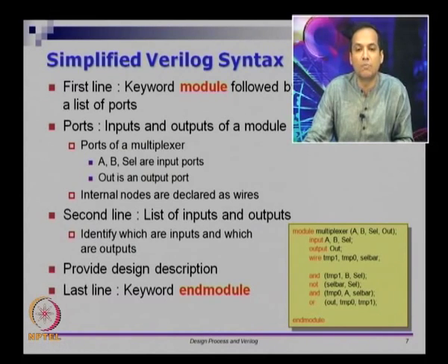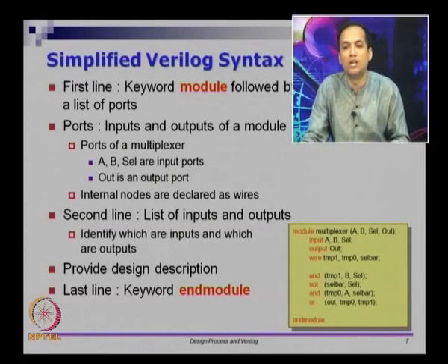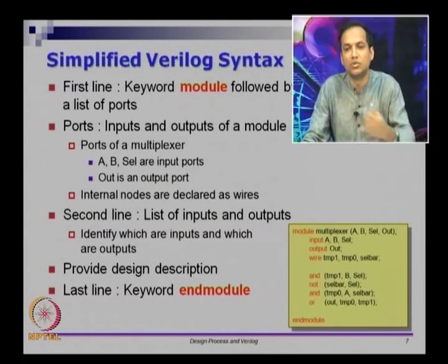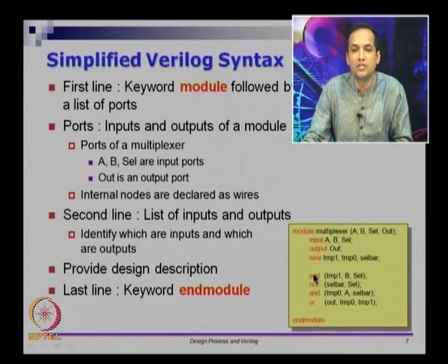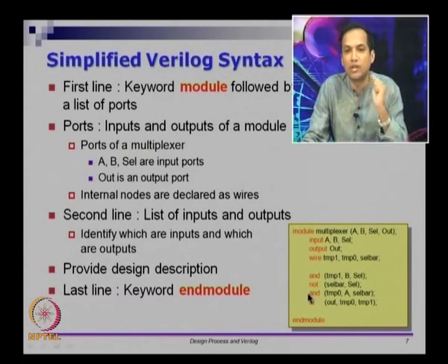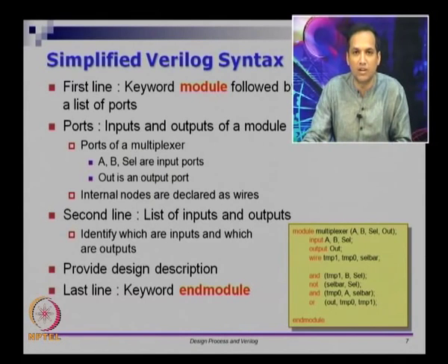They are called Verilog primitives. So these primitives are therefore Boolean functions, basic Boolean functions to be used directly. So in this case, this primitive takes 2 inputs and 1 output. So remember, all the primitives, AND, OR, NOT, XOR, all of these are actually just single output functions, right. So the first thing will be for the output and the rest of them will be for input.